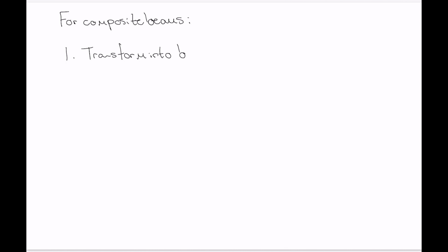Two, we calculate the dimensions for the transformed beam, so a new width dimension if we're dealing with moments occurring about the horizontal centroidal axis.